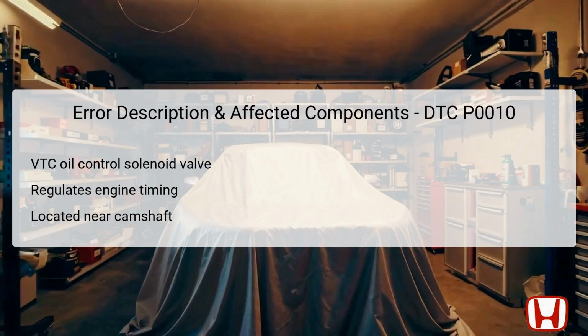The DTC P0010 specifically concerns the VTC oil control solenoid valve, a vital component in managing the variable timing in the engine. The VTC system adjusts the timing of the intake valves, which helps improve the engine's overall performance by optimizing airflow.